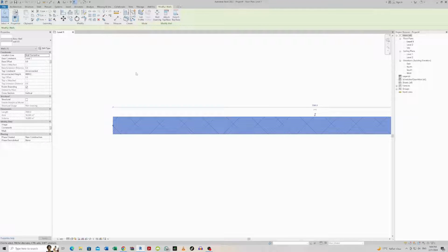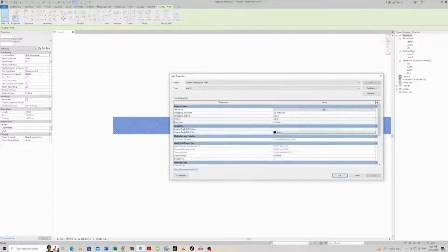Click on the wall and go to Edit Type to start adding new layers to our wall. The layers of the wall are displayed between two core boundaries separating the finish layers, where the upper one is facing the exterior side above and an interior side below. Stand on the core boundary and press Insert to create a new wall layer on both sides of the structure wall.